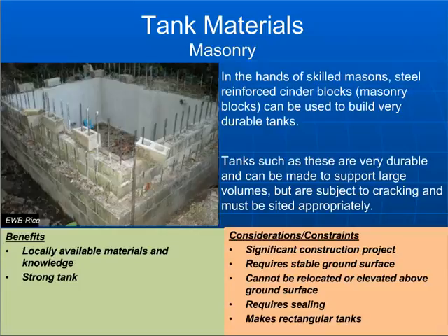The masonry tank is commonly used in a lot of developing communities. These tanks, though, require some type of skilled mason or very skilled labor in order to construct a watertight masonry tank. Again, depending on what's being used locally, that may provide a very clear answer as to what type of material you would want to use for your tank.